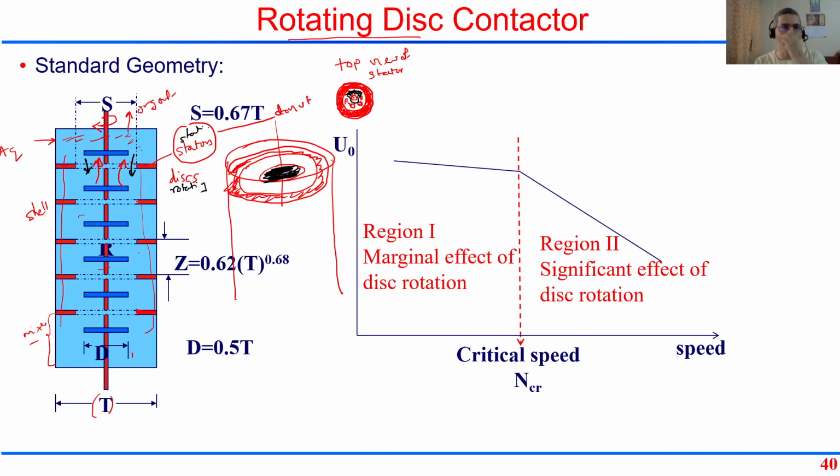So it does provide a counter current contact, and the extra agitation provided by these rotating discs creates the breakage of drops. So we are no longer dependent on the large drops that are generated by the distributor. We can break them down into smaller drops so that we can get good mass transfer, good interfacial area. I hope you people are able to visualize. If not, pause and watch a video, or pause and think, and maybe read some research paper.